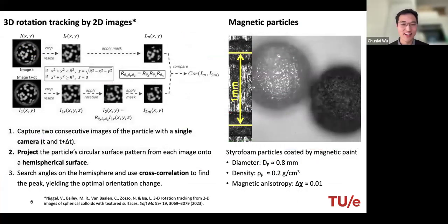That's a very good question. I would say this is one of the biggest difficulties in the whole preparation for the setup. The particles have to be small enough to be comparable with the size of the Kolmogorov scale of the turbulence, which is decided by the size of the setup. They also have to be light, because we want those particles to go into the vortex filaments, and they have to be magnetic enough to interact with the field.